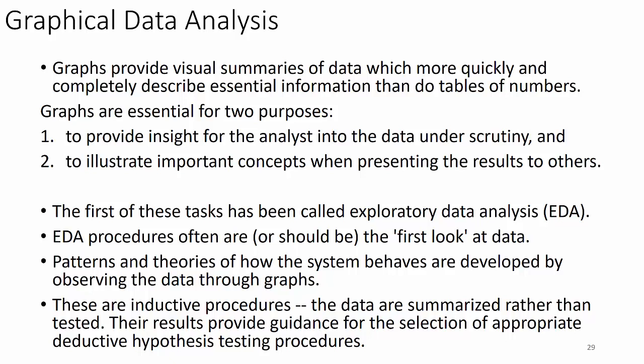When I get a bunch of rainfall data over time, even if it's 20 years' worth of 15-minute data, I plot it. By plotting that, I can see where the storm events are, because they're clustered. I plot the intensity of the event over time, and I can count real quickly the humps and the curves, and I can count how many storm events occurred over that period of record, even if it's 20 years. And I can also get a sense for what the extreme events were, the long ones and the intense ones.